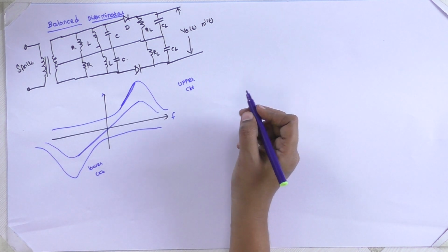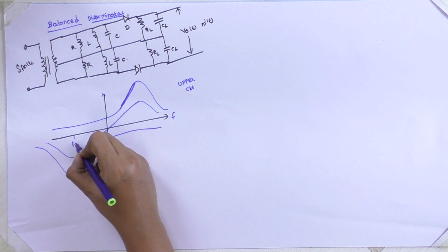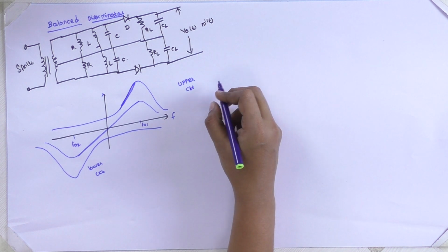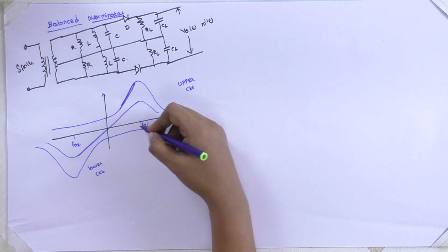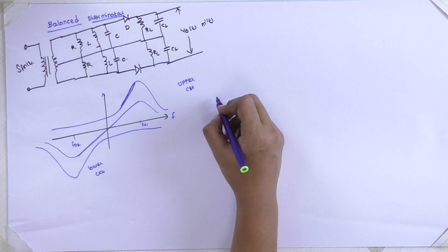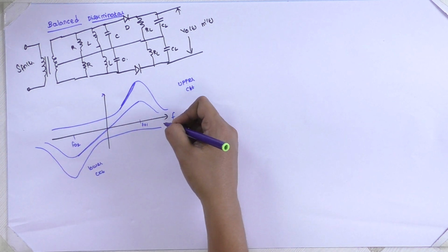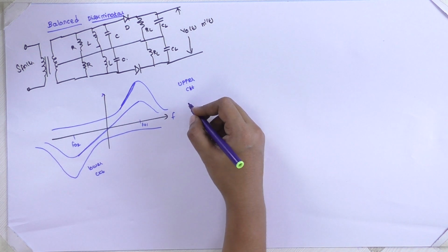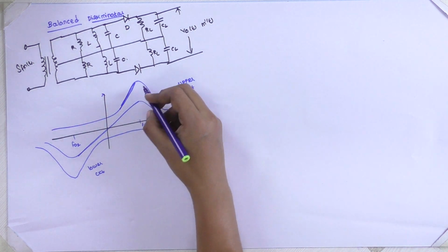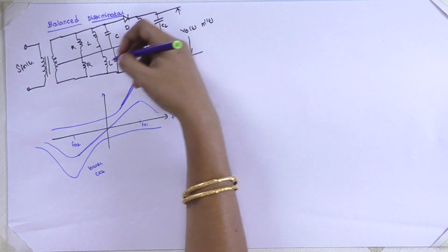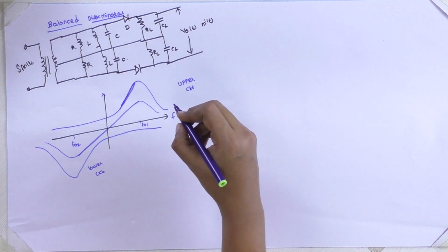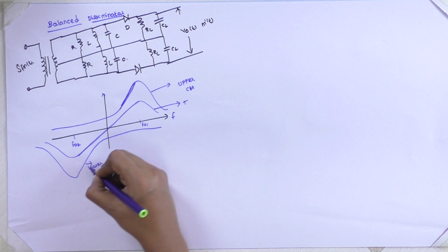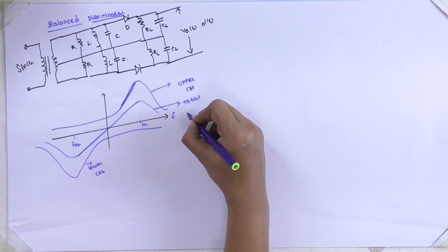Our linear region will get expanded from F0 of 2 to F0 of 1. Instead of, as we have seen in the previous circuit, our resonant frequency being only at F0, here we have F01 and F02. This is the total response of both the tank circuits, that is the upper and lower tank circuit or upper and lower slope detector. This is the total response. This is for the upper curve and this is for the lower curve. This is the total response.